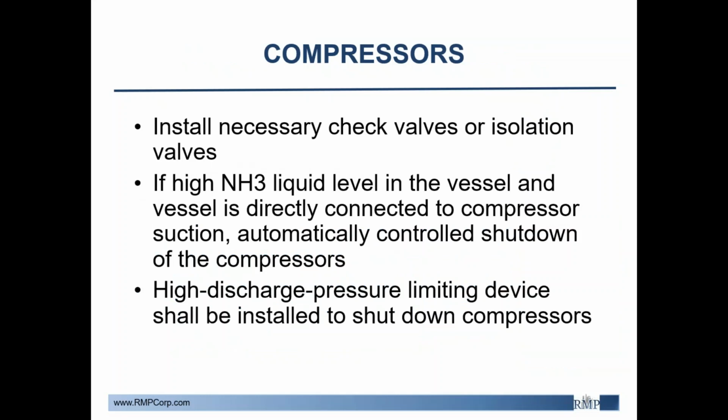As far as compressors are concerned, looking at where isolation valves may be and if there are more that are needed to take a compressor offline. Looking at automatic shutdown overpressure protection. They count as safeguards, so it ties in the PHA, but it's also one of those best practices, and not only for business but also for safety.